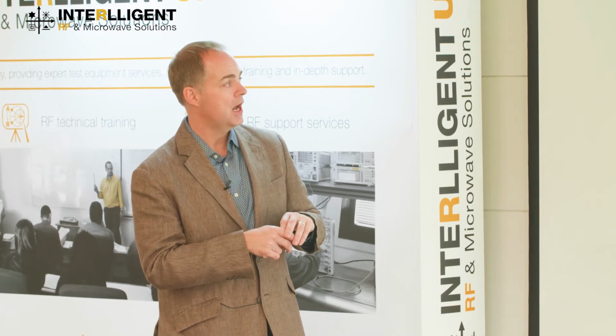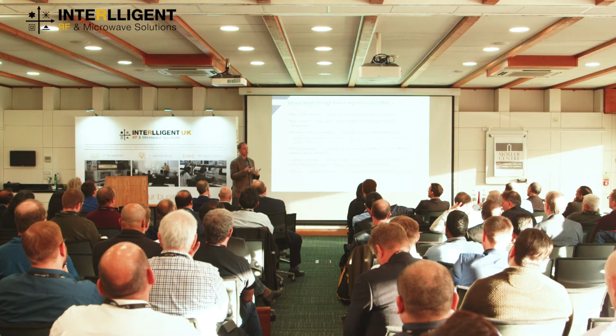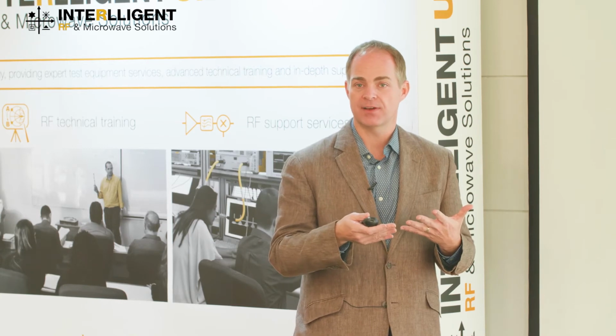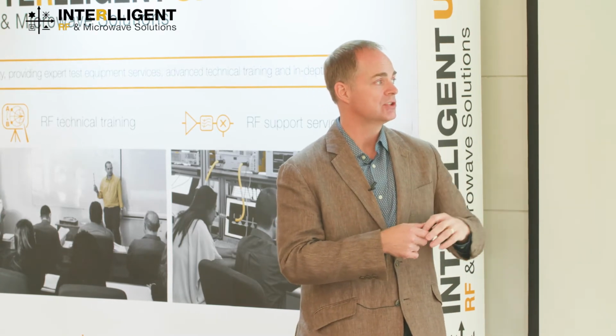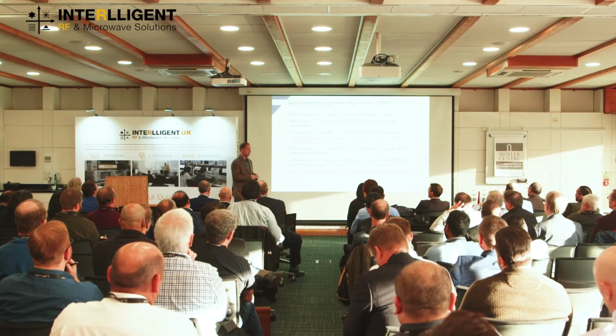We need minimal dispersion, so trapping again is a native part of gallium nitride technologies, and that's really kind of intrinsic to how the high power density and the wide band gap is achieved. The epitaxy actually has to have some trapping in it due to the nature of the device. But there are things that can be done to mitigate that. And we've been working on that in order to get the minimal dispersion so that it doesn't have a negative effect on your efficiency and on your linearity.